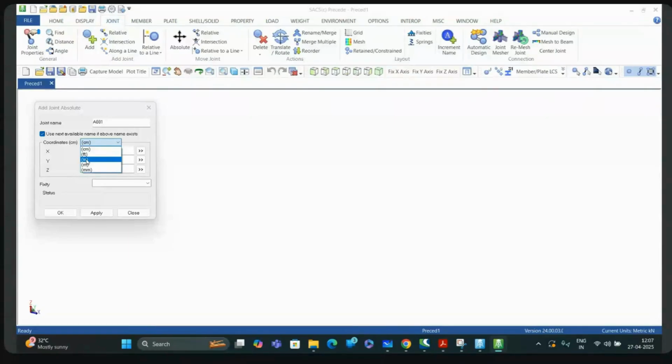At that time, for modeling, it will be easy if you toggle the units over here. Now I am selecting M. I am trying to create a centroid. If you click on tab, it will go to the next field, the Tab key on your keyboard. So it will save you from manually hovering the cursor over the fields.